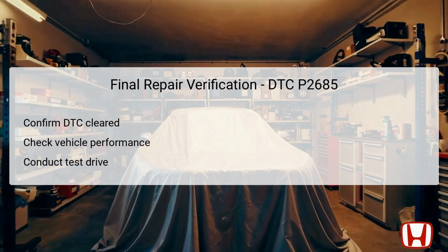necessary. After completing the troubleshooting and repair process for DTC P2685, it is essential to conduct a final repair verification. Begin by confirming that the DTC has been successfully cleared using the HDS. This step ensures that no residual error codes remain in the vehicle's computer system.